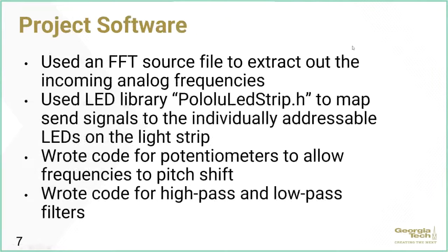The project generally uses an online compiler provided by Mbed. It is free to use for everybody, so I recommend using that one. For the code, we have used an FFT source file available to us, which allowed us to go from the time domain to the frequency domain in order to get the frequency that we needed.